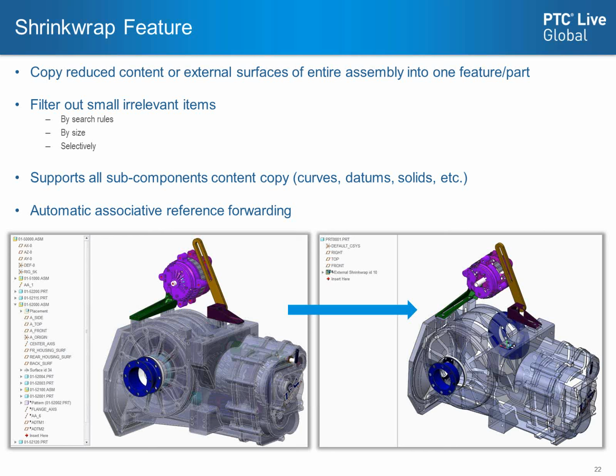It's basically used for simplifying a very large assembly into a single object that contains some or all surfaces or geometries from the original assembly. It can be used either simply for simplification. If you don't want to load the entire subassembly into memory every time you work with this assembly, you can prepare a shrink-wrap and next time load only that shrink-wrap instead of this subassembly.